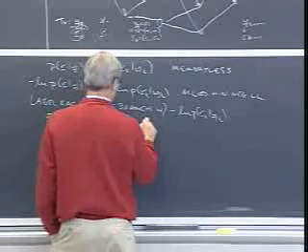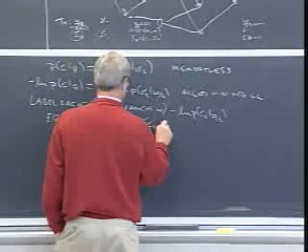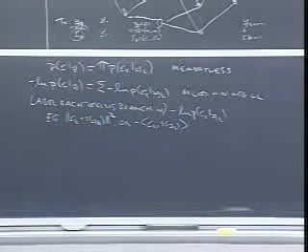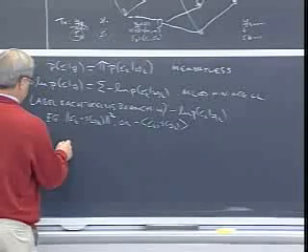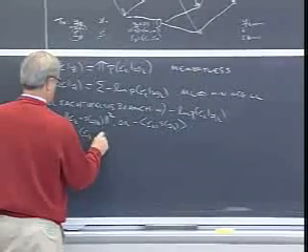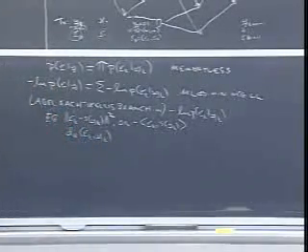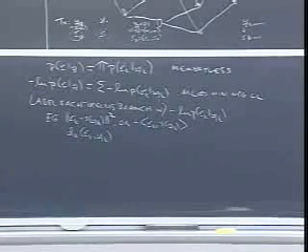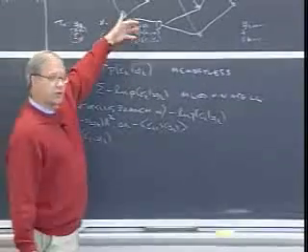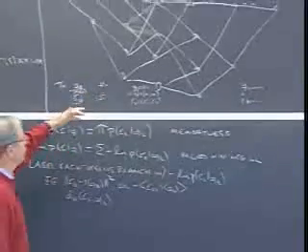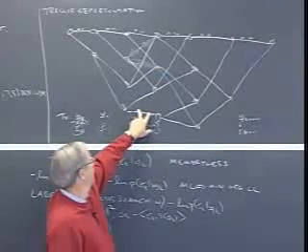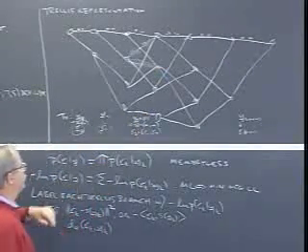Or, equivalently, minus the inner product, the correlation between Rk and S of Yk. We know these are equivalent metrics. Or on a binary symmetric channel, it might be the Hamming distance between what I received and what I transmitted, both of which would be binary two-tuples in this case. It's just some measure of distance, log likelihood distance, Euclidean distance, Hamming distance, between the particular thing I would have transmitted if I'd been on this branch and the particular thing that I actually did receive.